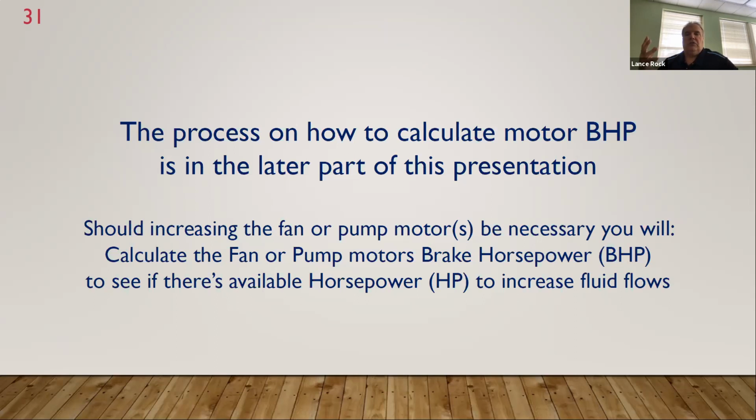You just don't want to start increasing flow without actually knowing what the actual available brake horsepower is. We don't want to have a 30 horsepower motor in there and we're operating at 29.5 brake horsepower and just start adjusting a pulley or changing pulleys and going past the nameplate rated horsepower, or the installed heaters, breakers, fuses on any one system. So you basically want to read your airflow and then immediately calculate your brake horsepower for the system you just read those hydronic or airflows for.